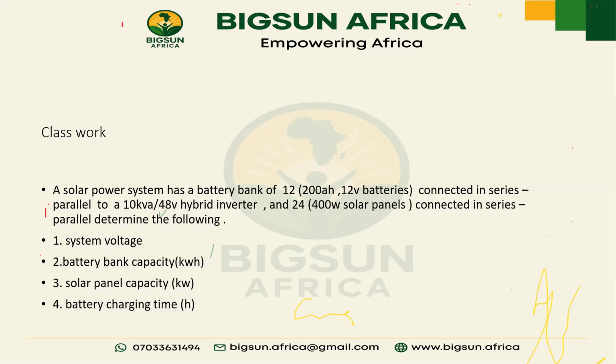So another thing we are now looking at: if you calculate your charge time and it is not commensurate with the peak sun hour. In Lagos we'll use 4.5 or 4, in the north we'll use 6 hours or 5.5, in Abuja we'll use 5 or 5.5, right?